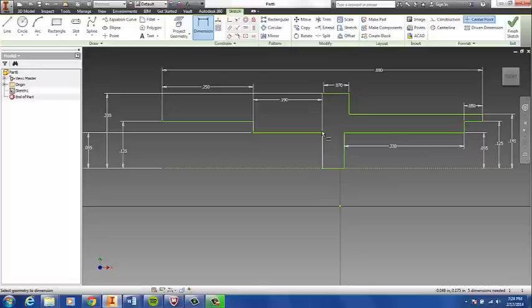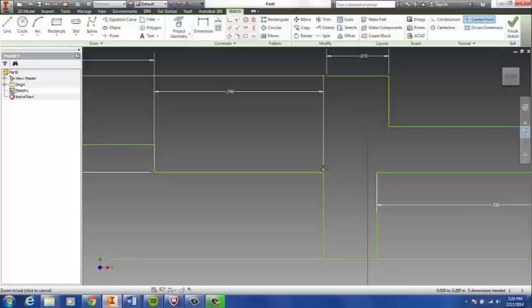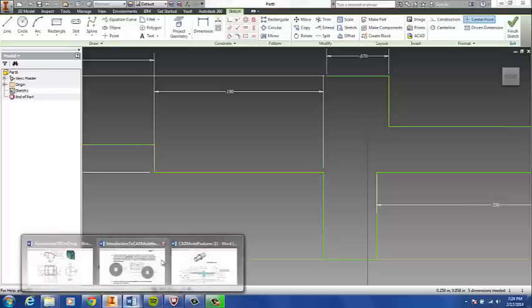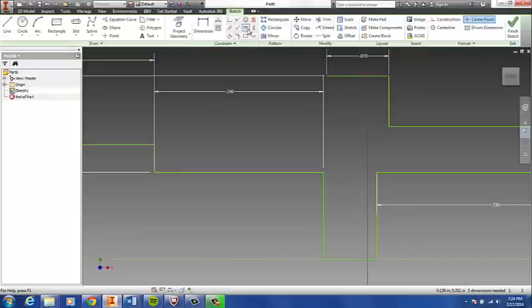Okay, now it looks like it moved this line in. Let's zoom in on that. Yeah, you can see this line doesn't meet there, and it clearly does on the drawing. The extension line here actually extends into the drawing to show you that these two lines should have verticality. So we can use the vertical constraint, that point, and that point, and then that will shift over.